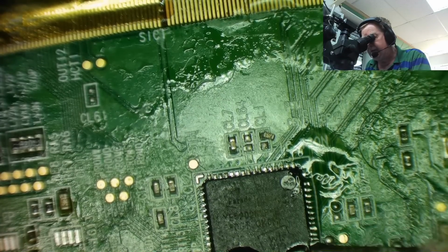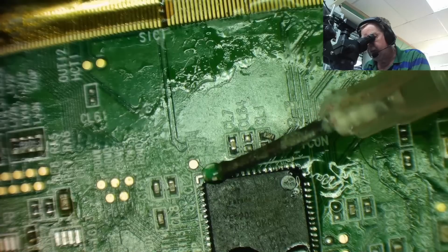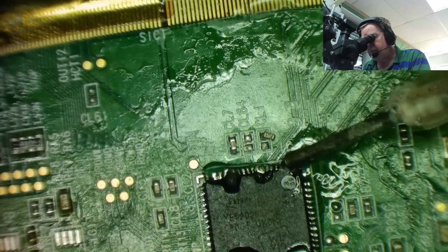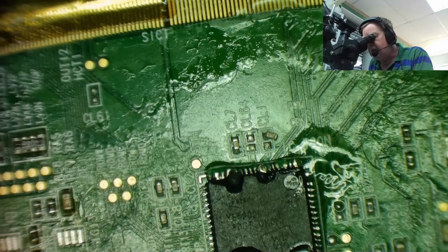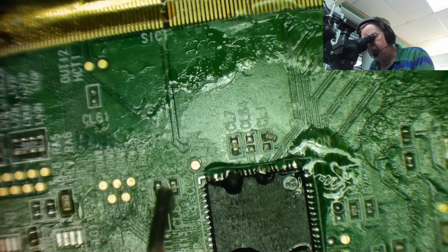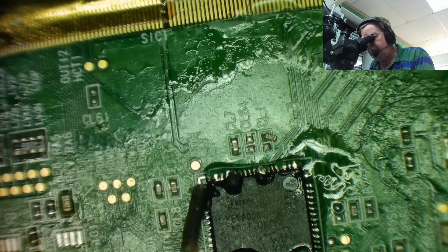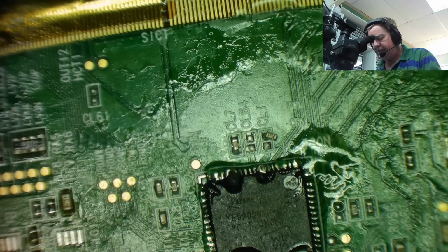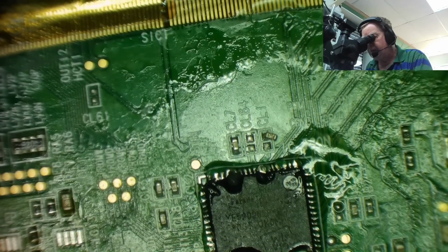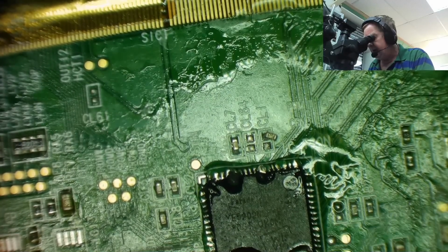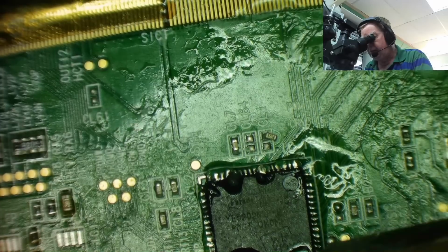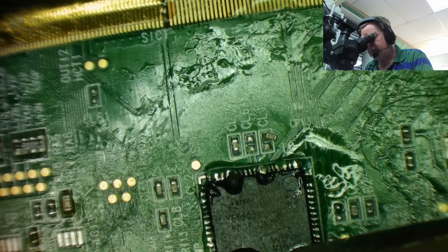Probably afterwards I'll get the hot air on it just to make sure I've got a good solder joint all the way around it. But if we solder it in place first, then the tension of the solder should keep it still while the hot air finishes the job. And of course I can't solder the centre pad underneath this way either, so I will need to use the hot air on this afterwards. The idea being that there's leaded solder on now, the melting point is lower than the lead free, of course. How many times have I said that? Too many.